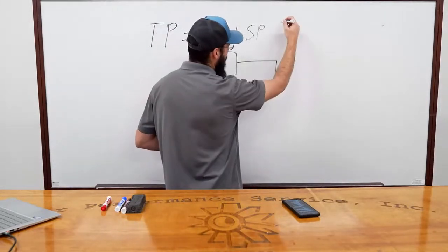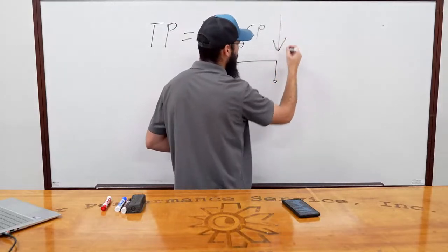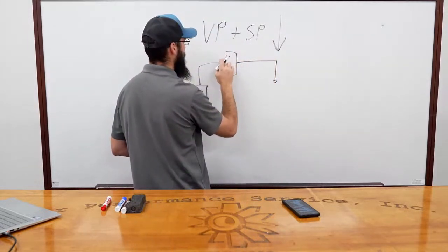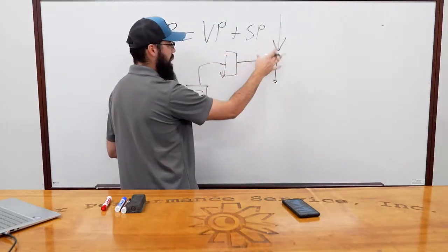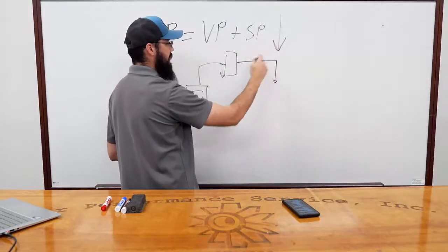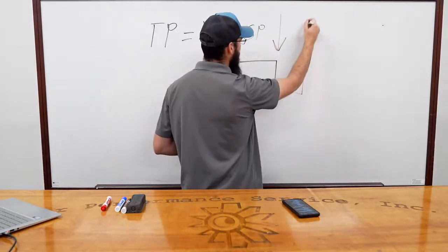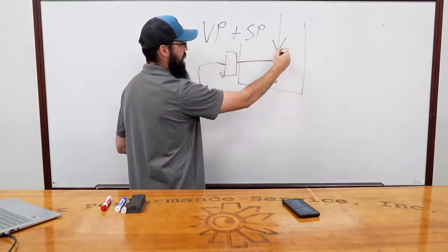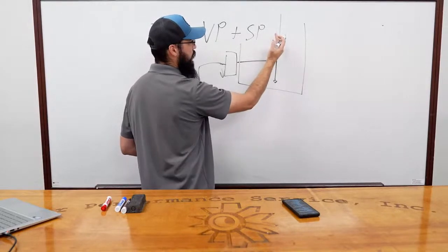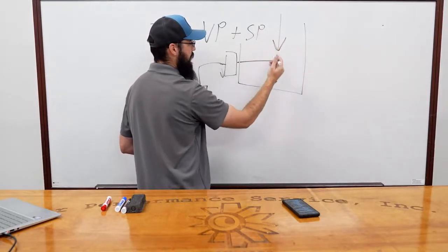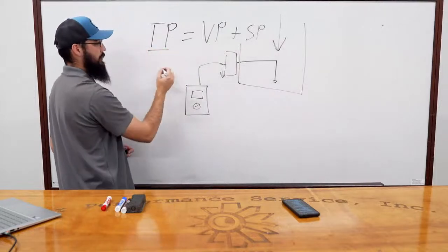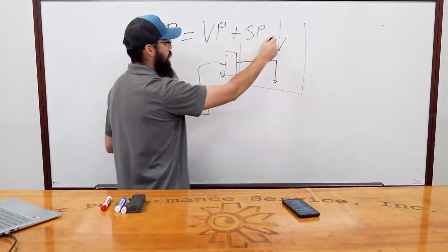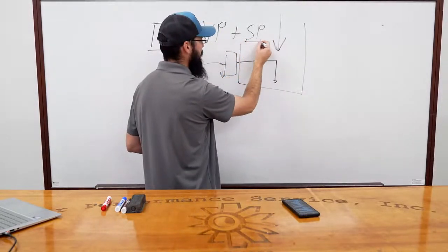So your airflow in this case would be this direction. So if this was sitting, I technically drew that backwards, didn't I? If this was sitting in an airstream, let's say this was a piece of a duct, it's flowing, you want to read this side, because this side, if you point it towards the airstream, then you're going to get what's known as total pressure, with the probe facing into the air. With it facing away from the air is where you get your static pressure.